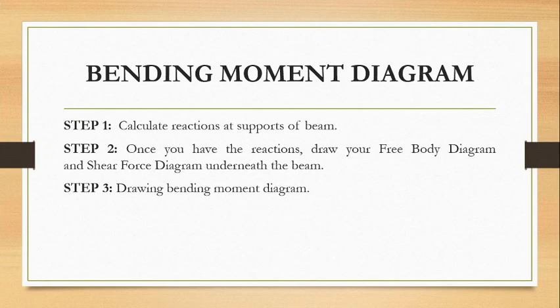But in practical life, economy and structural efficiency don't go side by side. Most of the beams are made rectangular because they are cheap, even if they are less efficient. But in case of bridges and large span structures, structural efficiency is more important. Therefore, instead of using rectangular beams which have more self-load, we have started making I-shaped beams or T-shaped beams. These shapes have less material, but they are much more efficient than the regular rectangular beam.